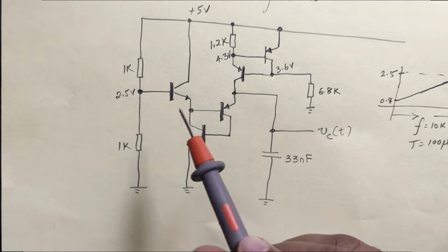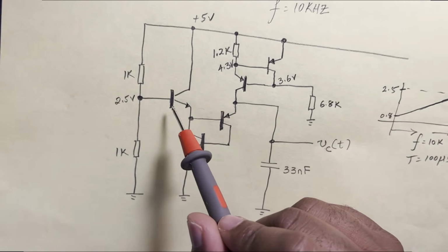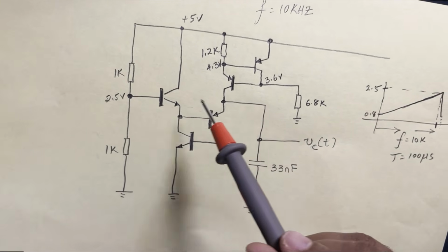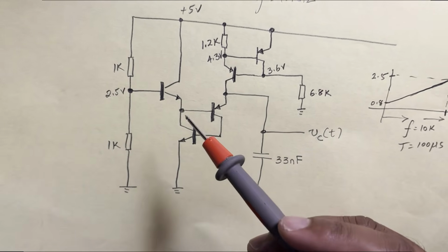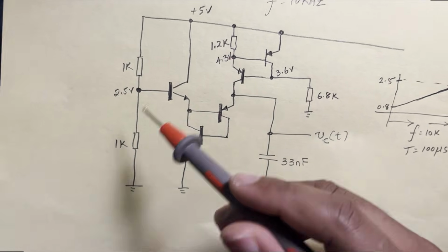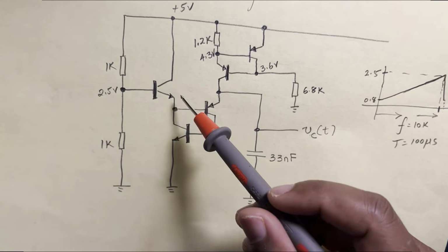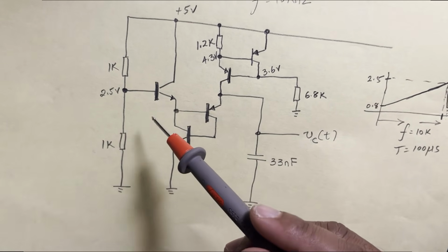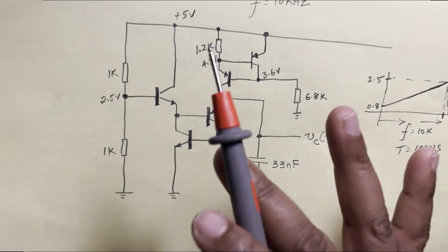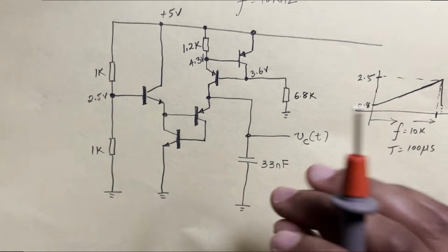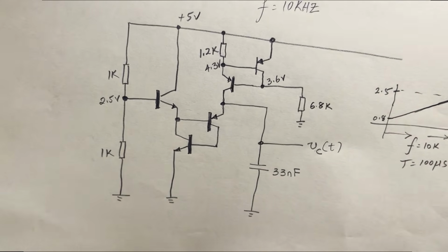All right, so now the transistors I'm using are just generic, any kind of transistors that you can get, the BC550, 450, or 545 combination of PNP and NPN transistors, or the 2N3906 and 2N3904. You can use any standard generic low power transistors and you should be able to get this working, right?